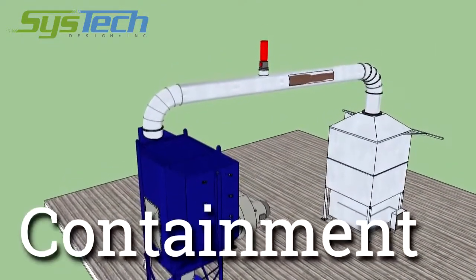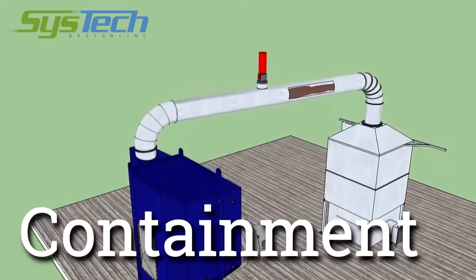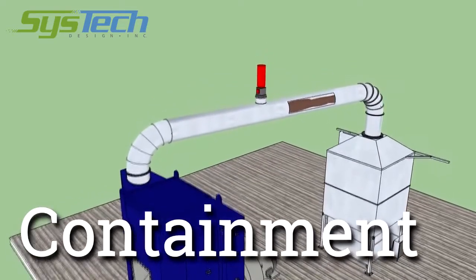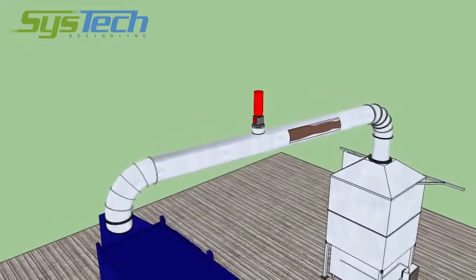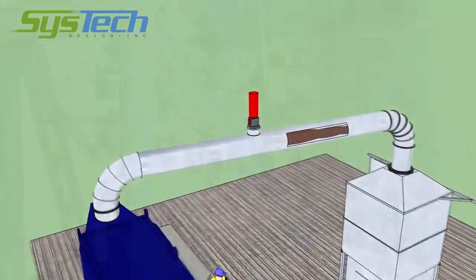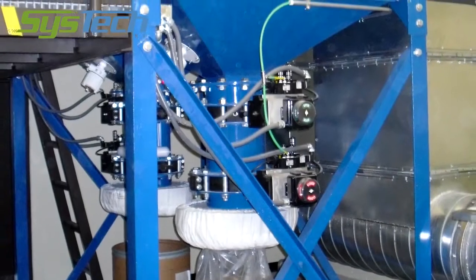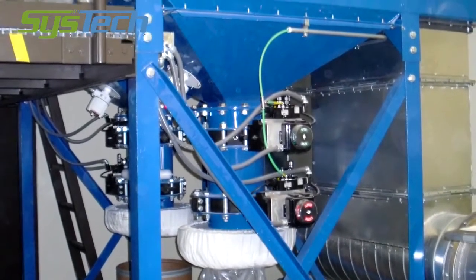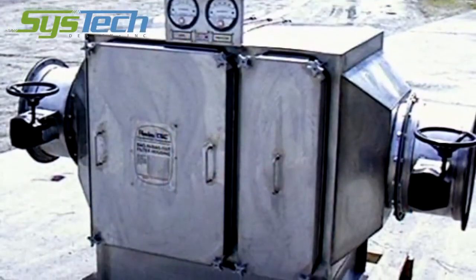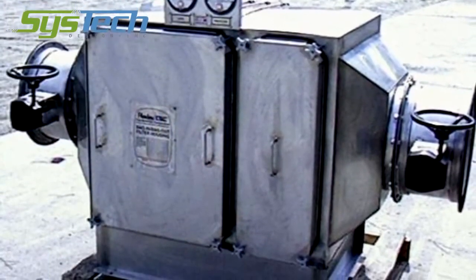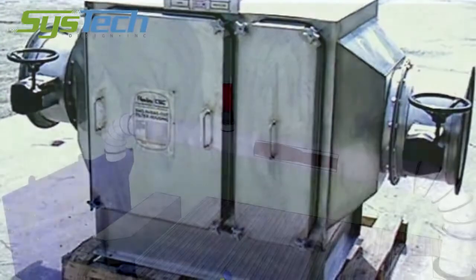The final and seventh C is containment. Handling of toxic or potent compounds necessary in some pharmaceutical facilities includes features to curtail exposure of the employee to the particulate or compound. The dust collector body is fabricated to have a higher specification. Associated equipment includes bag-in, bag-out filters, double valve bag-in, bag-out hopper discharge, and bag-in, bag-out HEPA filter assemblies.